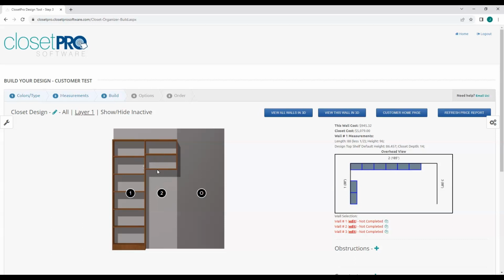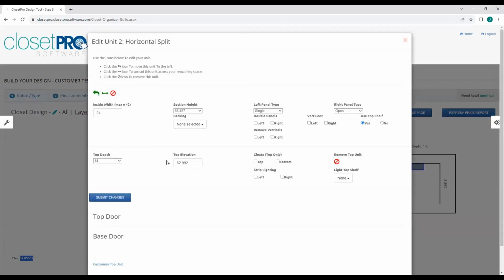And we're just going to use 2 of the things that I've just walked through to align these. So if I click this shelf, I see that the elevation is 59. I'm just going to grab this. And to align these, I'm going to put this into our top elevation field.